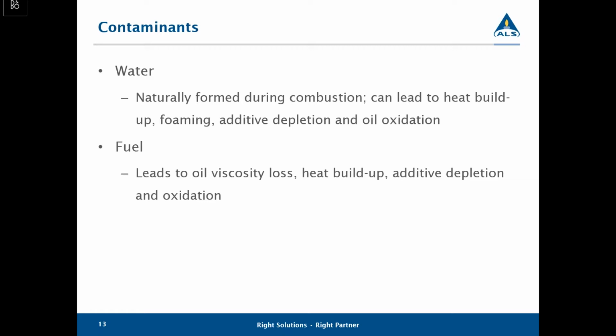Fuel is another contaminant that we see often in engines. The main thing that it does is it causes viscosity loss. So you can think of it as maybe you have a gravy and it has a lot of flour and it gets a little bit too thick, and you were to keep diluting it with milk, it would lower the viscosity of that gravy. So that fuel is doing the same thing to the oil. Fuel has a low viscosity, and as it mixes with the oil, it causes the viscosity to drop. And then with that viscosity drop, obviously the engine's going to lose its ability to lubricate properly. That's going to cause heat buildup, and then it's going to as well deplete the additives. And a lot of those additives are there to prevent oxidation and counteract acidic compounds. And so as you dilute those, that oil is going to degrade more rapidly.